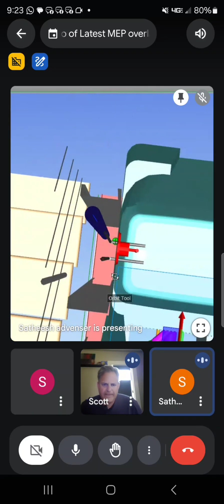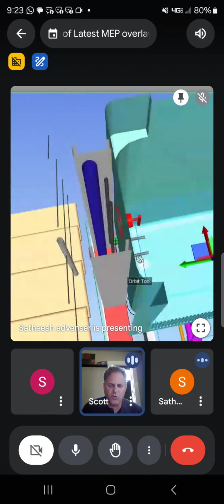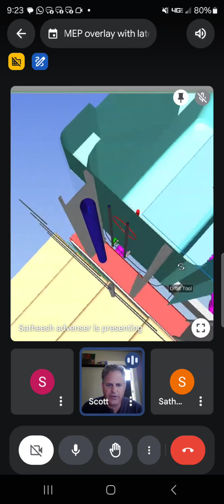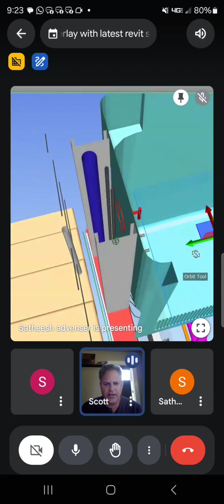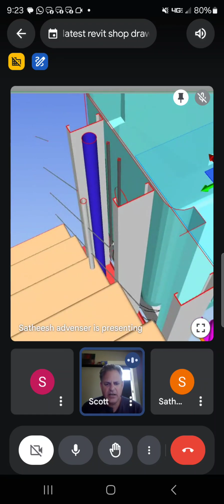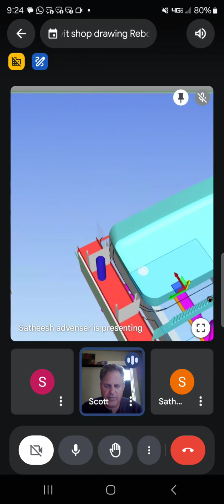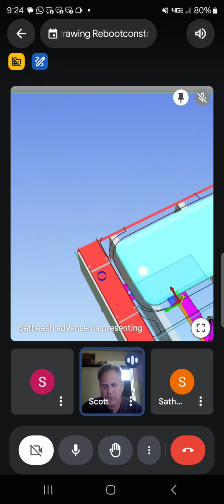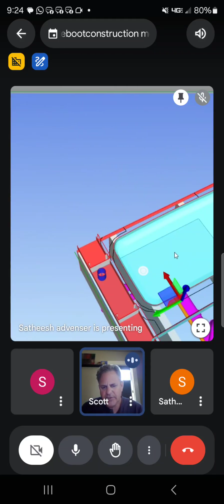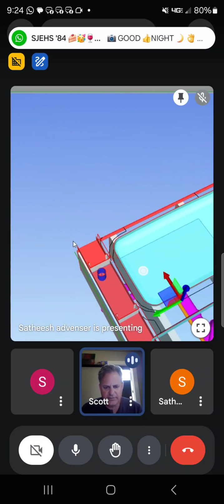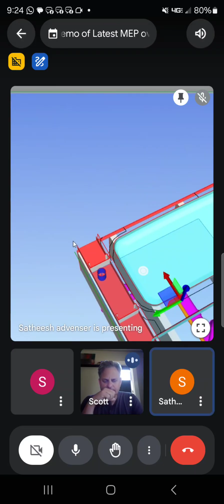Yeah. Okay. And then you can understand, in the wall itself, you can put a little 22-degree angle in there and then reconnect it again. What I was trying to get is anything coming up through the floor, if you can get away with it, try to keep it perpendicular to the surface that you're coming through, because when we drill it, we don't have to worry about doing two or three drills to get an oval angle. You know what I'm saying?